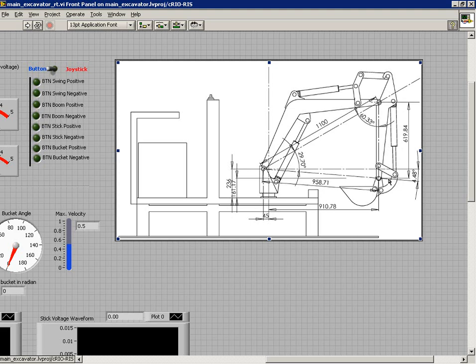Last time we tried to use on-off control. On-off control means that when it's on, it's moving, and when it's off, it's not moving. So we thought that by changing the time of on and off, we can use PWM.